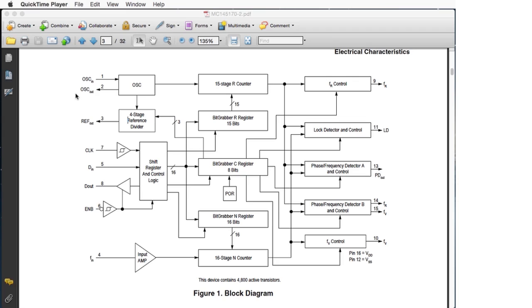It's got a 10.24 megahertz crystal elsewhere on the main PCB, which runs the whole radio. It's mixed in various ways, but that's fed down to the PLL section to generate the reference. That has a reference divider, a fixed value inside the chip that doesn't change. In this particular chip, it's configurable.